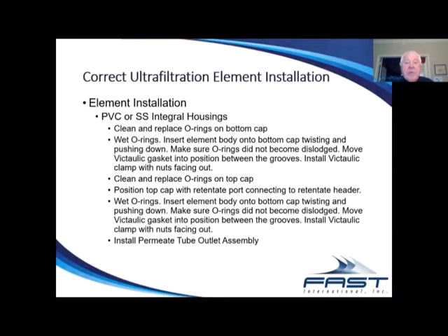For the integral housings, it's very similar. Clean and replace the O-rings in the bottom cap. Again, always wet the O-rings, insert them twisting to make sure you don't dislodge the O-rings from their grooves or cut or damage the O-rings. Install the bottom clamp with nuts typically facing out on the bottom clamp.